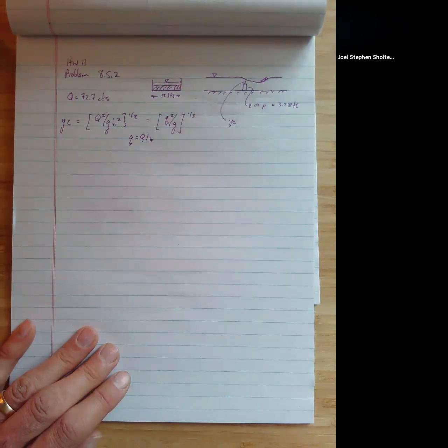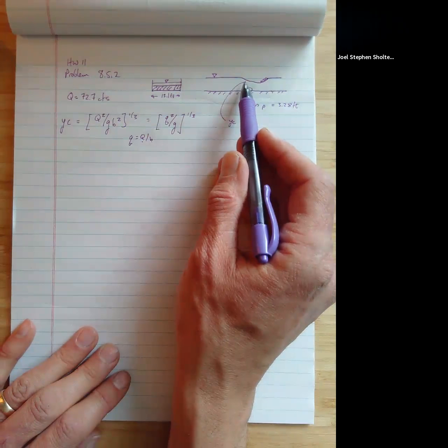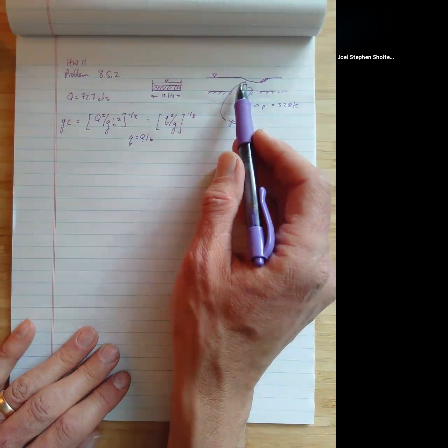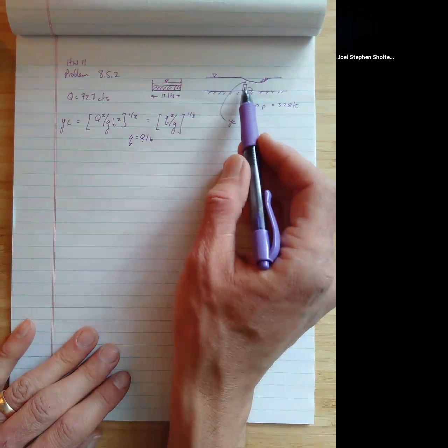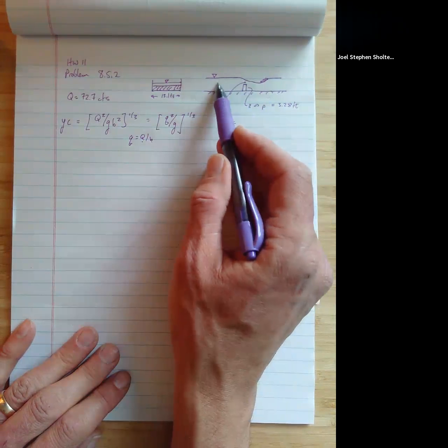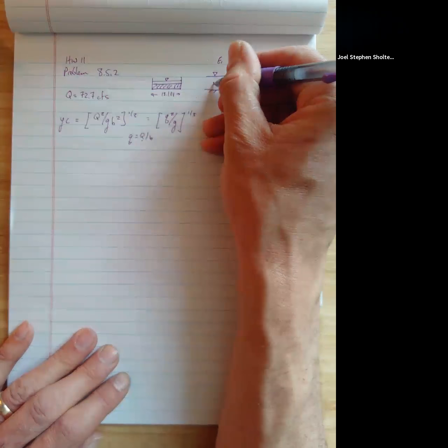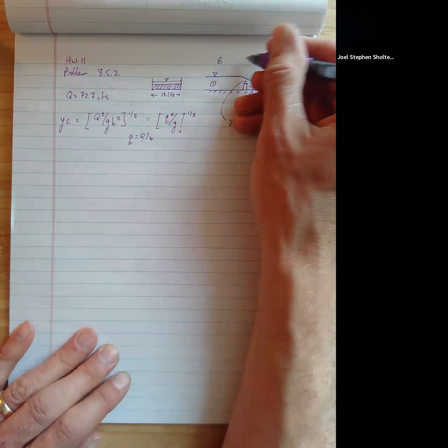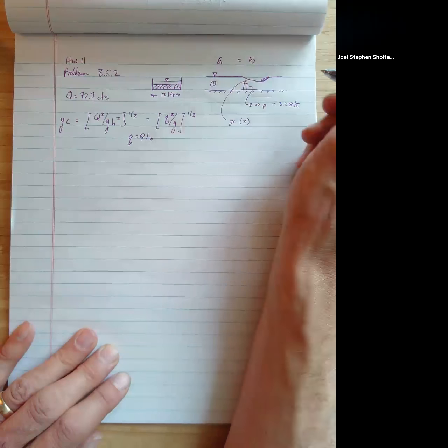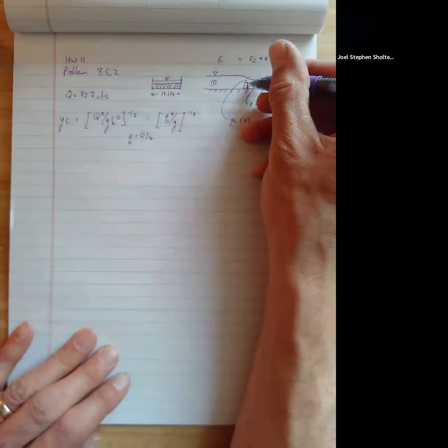So step 1 is we need to find the flow depth over here at the weir. And then step 2 is we go back to the energy equation that we did for weirs and flow approaching weirs, and we're able to back calculate this discharge using this specific energy equation, which just states that E1, this is point 1, this is point 2, is equal to E2, which is also the critical depth, plus Z or P or whatever we're going to call this height right here.